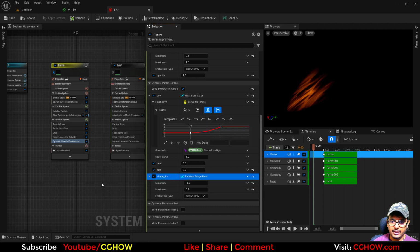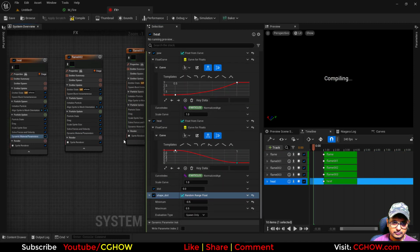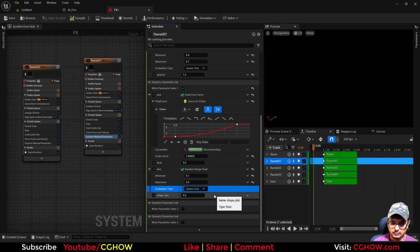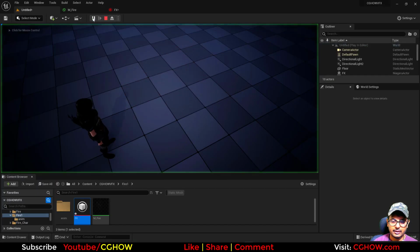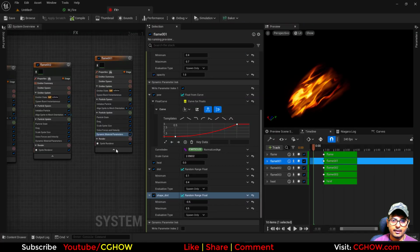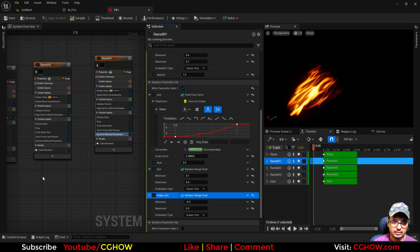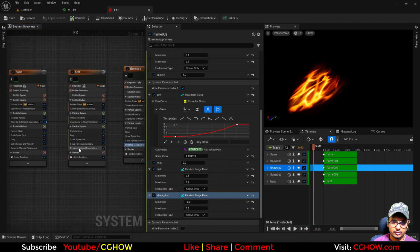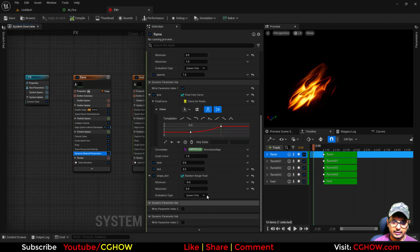And I'll copy that and I'll paste that in all my dynamic parameters. Now here you can see a little distorted shape, but it's cutting. So you can decrease it to 0.3, minus 0.3. So you can make that a user parameter so you will not have to change it for all emitters every time.